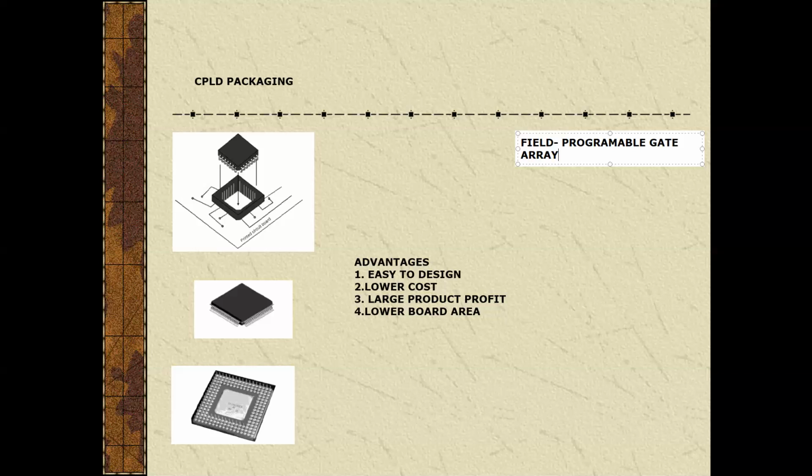The FPGA is larger than the CPLD devices, and the FPGA has a different architecture than the CPLD, which enables it to do more complicated functions and often contains memory in which data can be stored. Because of the design being different from the CPLD, the complexity of the FPGA is typically measured by the number of system gates on the chip and not by the number of macrocells.